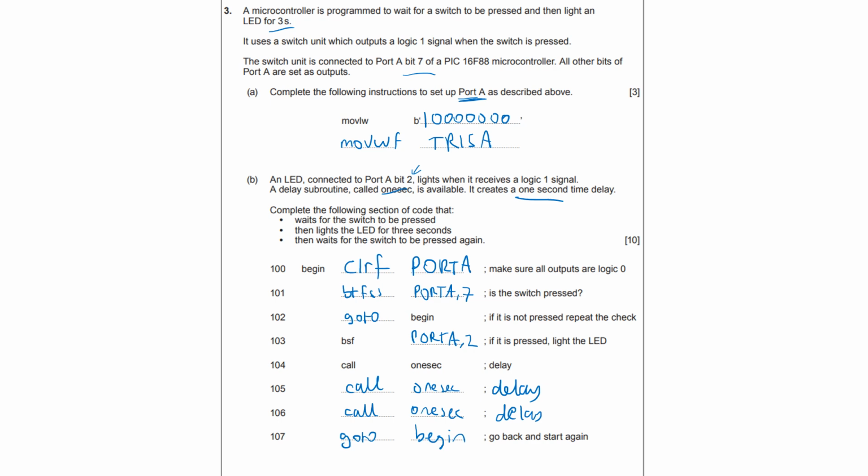Just so you know, if they're asking you about the interrupts, the INTCON register, it's bit 7 and bit 4 that need to be logic 1s for it to work. It even tells you that on the data sheet, so look on the data sheet and it talks about those 2 bits. And then obviously, when you do an interrupt service routine, you need to protect the contents of the working register.